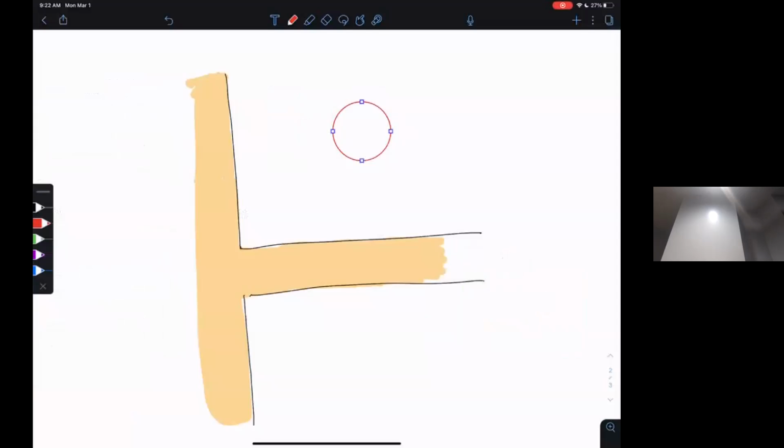Okay, so here is a corner that we want to cut. And this circle here, this is pretending we have this as our end mill. And it's cutting a straight line and all good. It's making a perfect cut. But when it gets to the corner, what happens? Yeah, it can't cut out the corner. So we're stuck with some material in here.